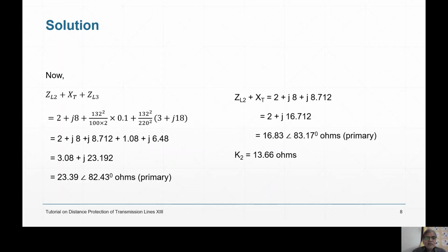But now if you want to go to the 132 kV line, then to which extent it will go to 132 kV line, for that you need to know location, which you are required to find out. And when you know location, then only you can know phi. So we are under trouble. So some assumption we will have to make. And therefore phi we will take for the whole line 132 kV. That much assumption we are doing. There will not be much error. I mean, there will be hardly an error of half a kilometer or some few meters. But then you see that we have to take because phi is unknown.